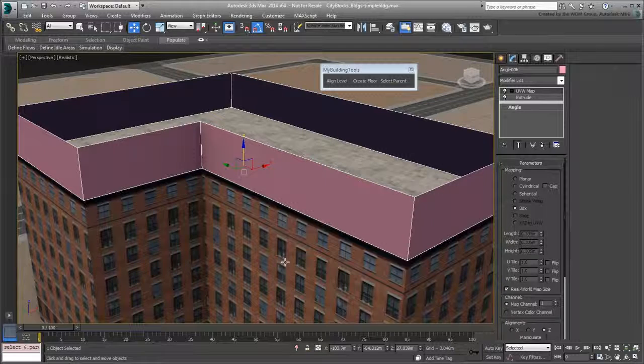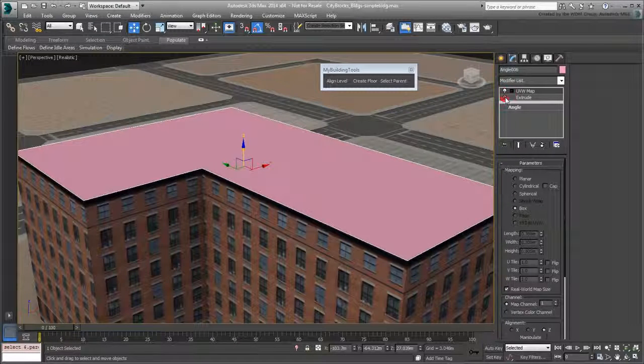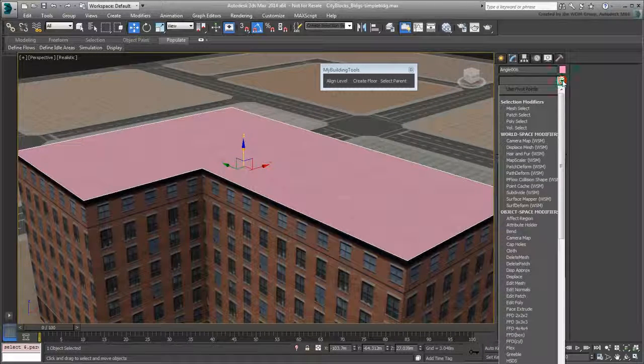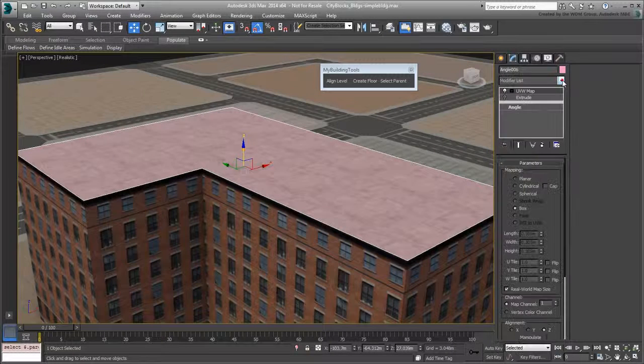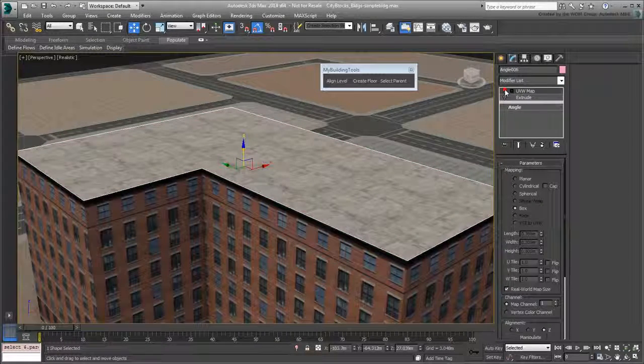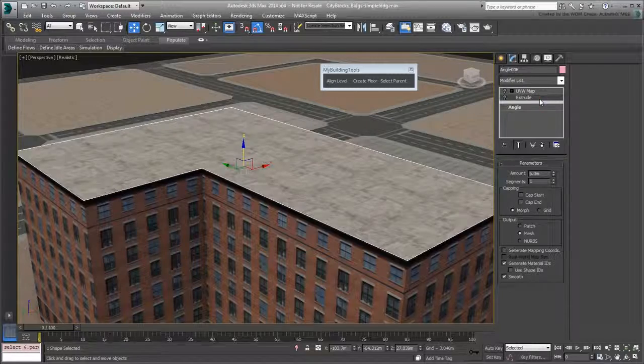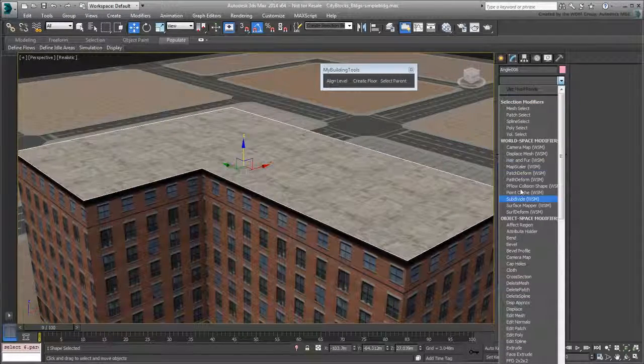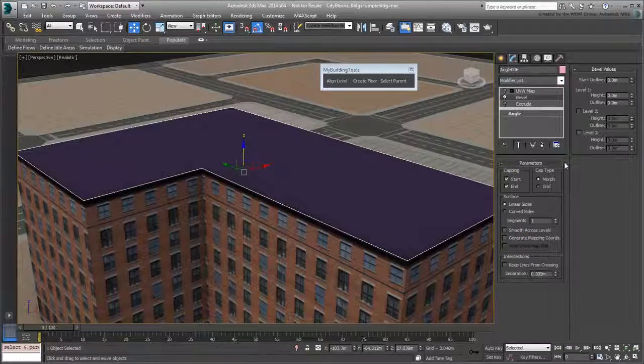Select the extrude modifier and then disable it. Try to add a bevel modifier. You will notice it's not listed. Like extrude, bevel works on 2D splines, not geometry-based objects. Because of the UVW map modifier on top, the object is now regarded as a poly object, not a spline. Temporarily disable the UVW map modifier so you can squeeze a bevel modifier underneath it, and then enable it again.